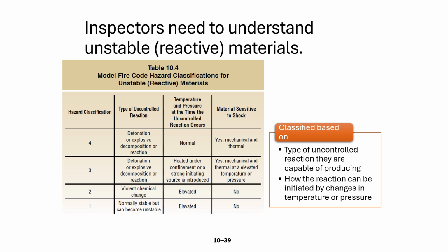Unstable materials can be found in the manufacturing of plastics, including expanded foams and urethane compounds. Blowing agents that create foam plastics are commonly classified as unstable and reactive. For plastic workers, examples of unstable reactive materials include hydrogen peroxide in concentrations greater than 52% by weight, ethylene oxide, and unsaturated polyester resin.